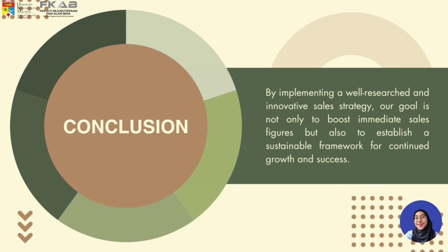In conclusion, our CFD simulation clearly shows that car body shape has a major impact on aerodynamic performance. We compared two 2D car profiles, one with a spoiler and one without, across 4 airflow speeds, and the result proved that the streamlined shape without the spoiler consistently reduced drag and provided smoother airflow, especially at higher speeds. This supports our hypothesis and aligns with past studies showing that aerodynamic optimization is key to improving fuel efficiency and vehicle performance. Our study also highlights how CFD is a powerful and cost-effective tool for analyzing airflow, helping engineers design better and more eco-friendly vehicles.